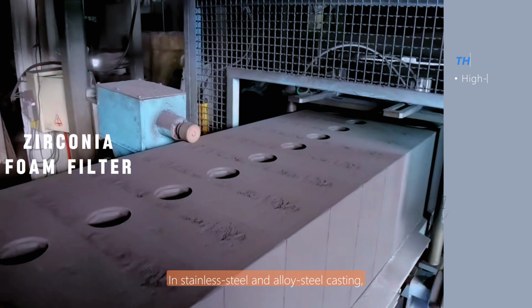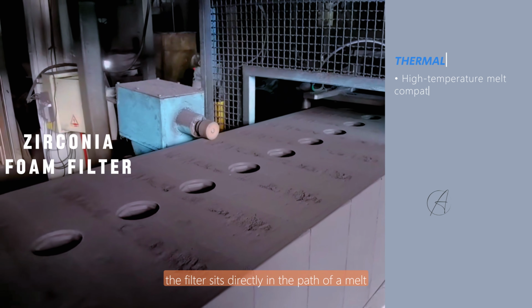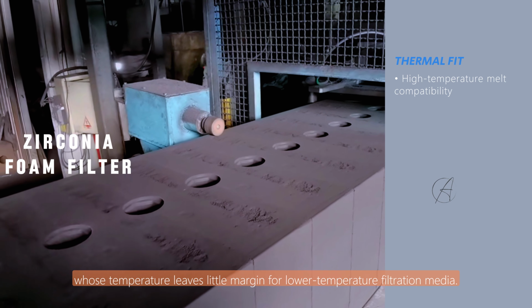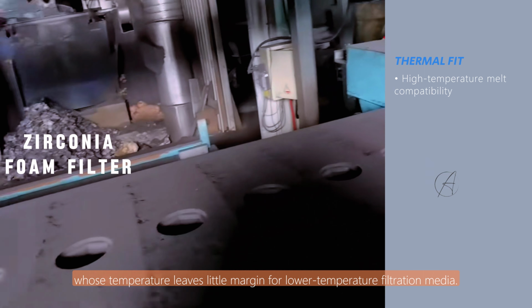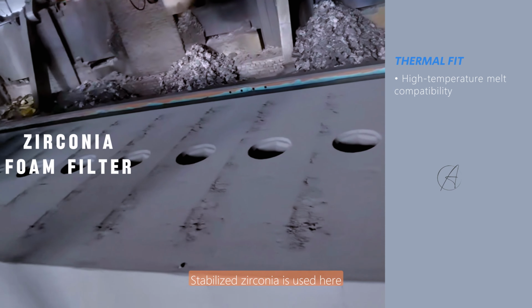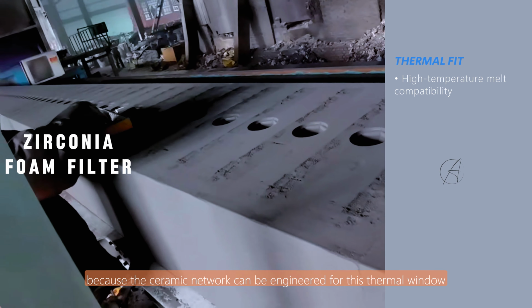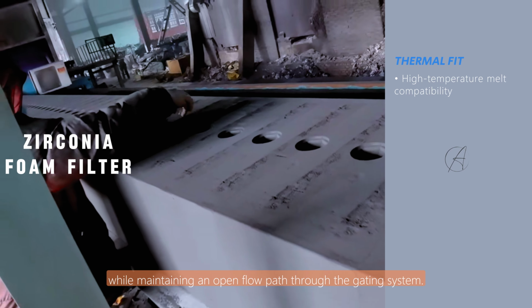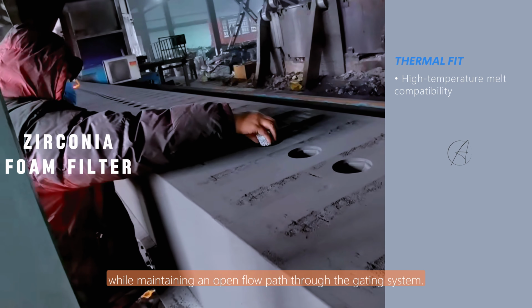In stainless steel and alloy steel casting, the filter sits directly in the path of a melt whose temperature leaves little margin for lower temperature filtration media. Stabilized zirconia is used here because the ceramic network can be engineered for this thermal window while maintaining an open flow path through the gating system.